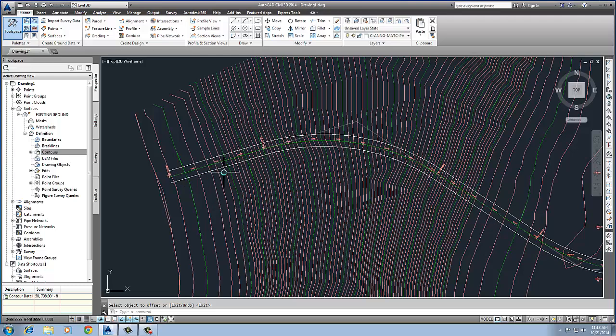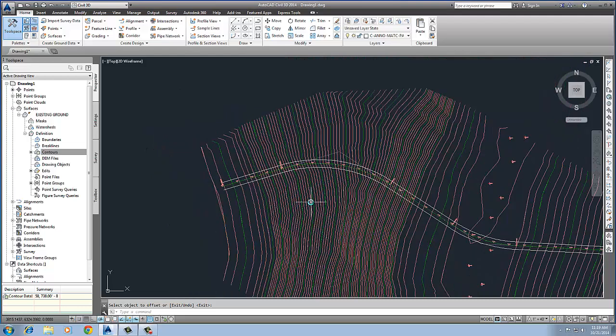You're going to have tangents, and you're going to have vertical curve information that we're going to be designing into this. So once we have our alignment here, we first have to sample the surface over which this is going to run to generate where that profile is going to be, and it's tied to that. And then we're going to generate the actual picture.